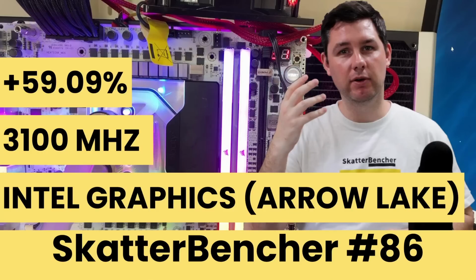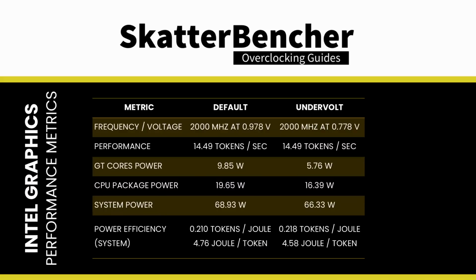For more information on how to overclock and undervolt the Intel graphics on Arrow Lake, I gladly refer you to SkatterBencher number 86. After undervolting the Intel graphics, we obviously generate the same 14.49 tokens per second. However, the graphics core's power is now 5.76 watts instead of 9.85 watts, which is a reduction of 41.5%.